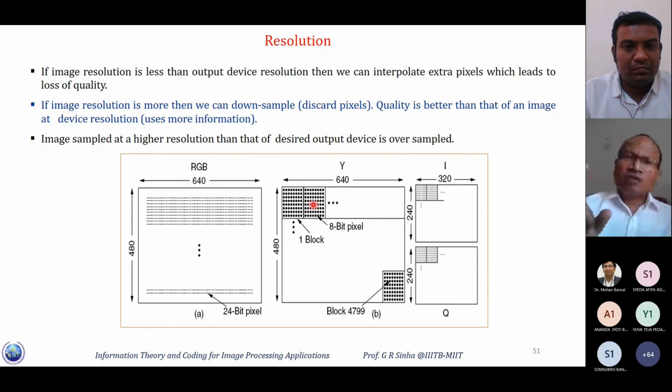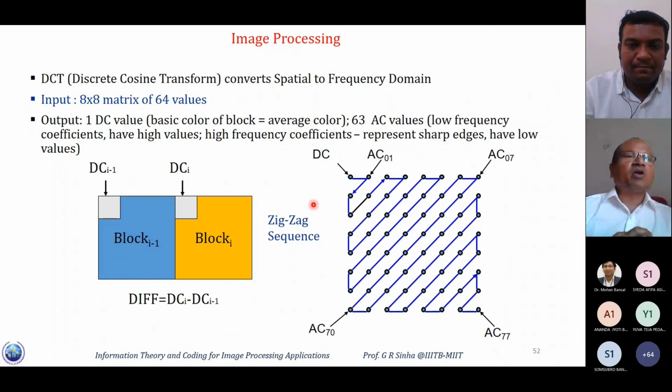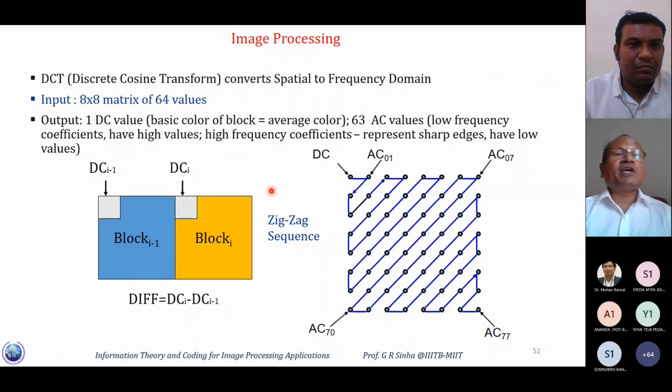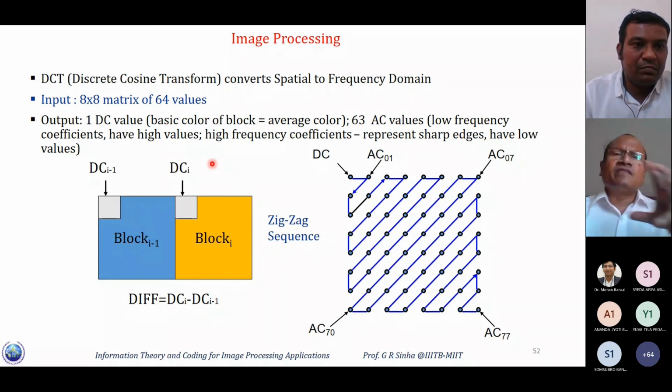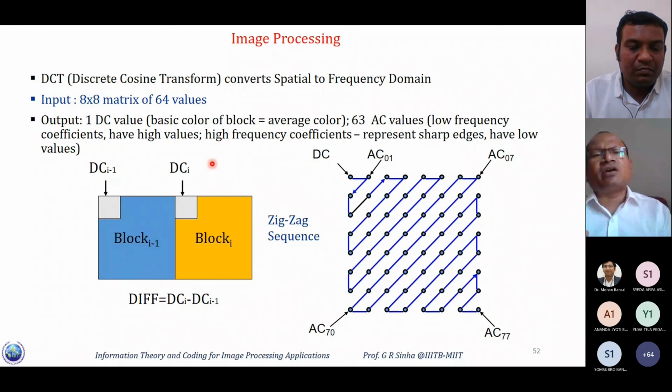And therefore we go block by block, so that we can check the redundancy, the correlation, and the similarity. This is why we do it block by block. Then we compute DCT, discrete cosine transform, or any other transform. You know about DCT: like we calculate the Fourier transform of the image, all pixels will be converted into coefficients, Fourier coefficients or DCT coefficients. So the DCT coefficients represent your pixels.